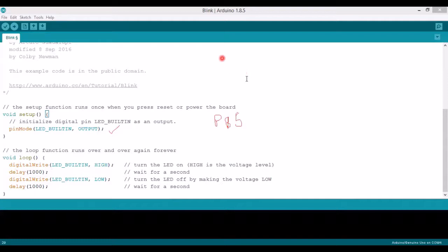if you look at this Atmel Studio code, which was originally PORTB = 0b00100000. So this is PB5. You set it as output. You initially set it as output.